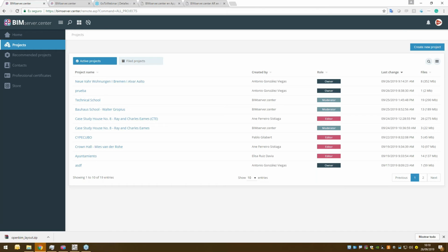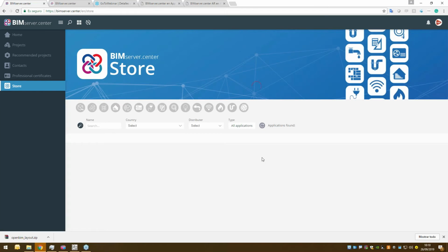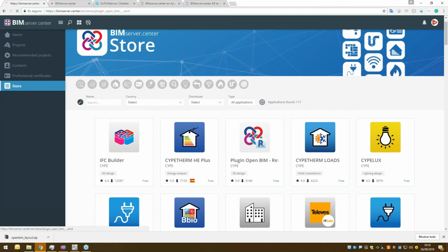When we detect that something is an IFC column, for example, we can read it as a column. If you define a chair as an IFC column, obviously we're not going to be able to calculate that. But because we are working with this IFC standard, we can usually read these kinds of elements when they are correctly defined. Also, when they have been made with Revit, we can read some of them using the free export plugin I have just shown you before.